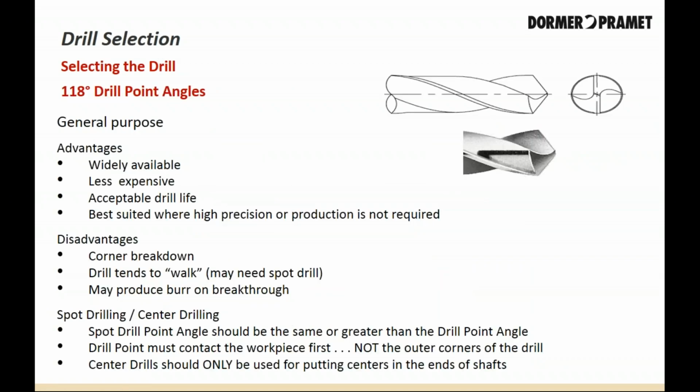The conventional point is the most commonly used drill point. Properly produced, it will give satisfactory drilling results in a wide variety of materials. In use, this type of point may eventually require some form of web thinning when used on drills whose web thickness has increased because of repeated resharpenings, or on heavy-duty drills with heavier web constructions. The conventional drill point does not have the self-centering capabilities that a split point drill has.